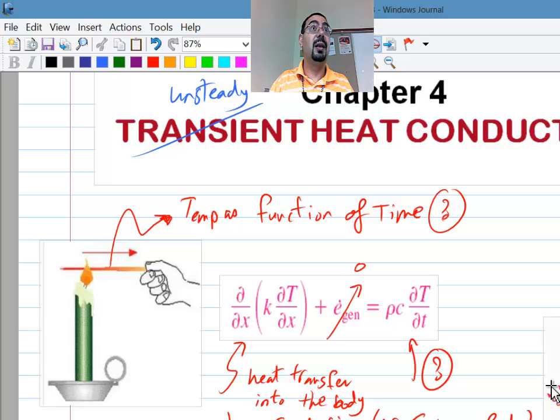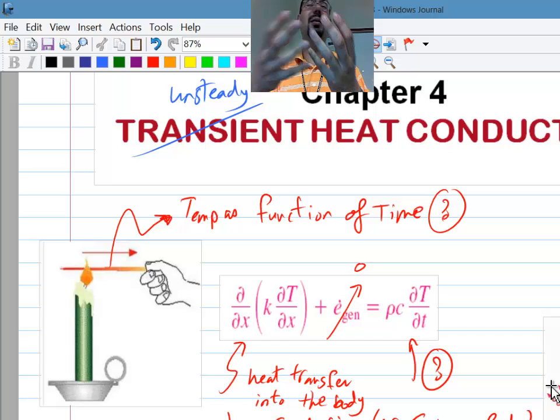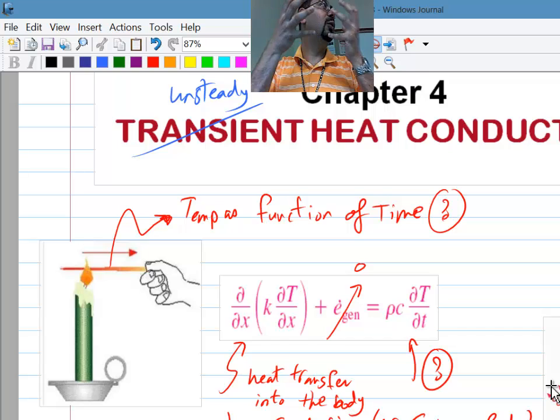Does K have to be high to do that? Excellent. Jason is saying that if you want to do this, you have to make sure K is big enough that you can say they are all at the same temperature. As in my discussion with James earlier today about this fan, it will never be just K. It will have to be a ratio between two things. One of them is trying to bring the whole thing to one lumped mass. That's what we call this approximation, lumped mass analysis. We bring the whole thing into one body at one temperature.